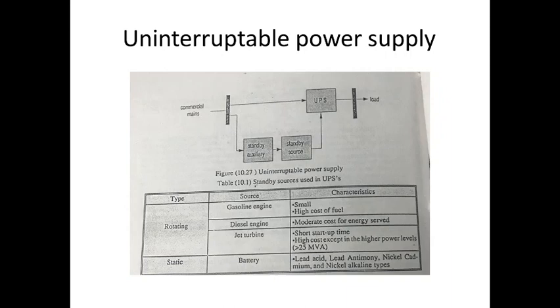Most installations have a regular maintenance schedule and regular testing schedule. Isolation from the line is excellent in standby mode, and rotating UPS may be the only alternative for higher power levels and most three-phase applications.